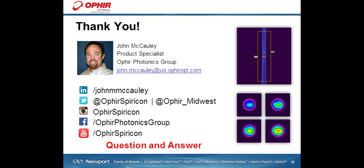So you do want to have a nice circular beam, obviously, or as close as you can get to it. But goodness of fit is really going to be, I would say, a better laser quality measurement. So it's going to be more of a metric of what you should expect the laser to be. So obviously, if you are expecting a Gaussian type profile, the goodness of fit is going to tell you how close it is to that perfect Gaussian fit, and therefore it's going to be a laser source quality measurement, where the circularity is going to be more of a laser system quality measurement. And hopefully that answers that question.